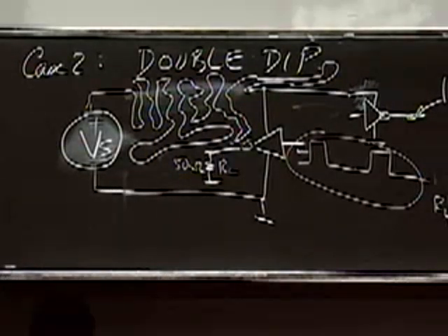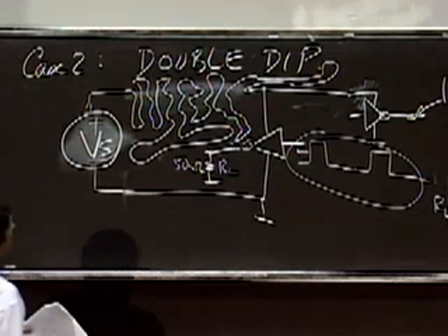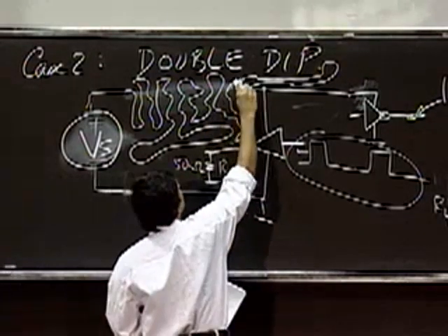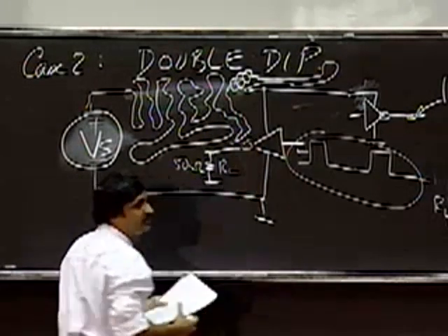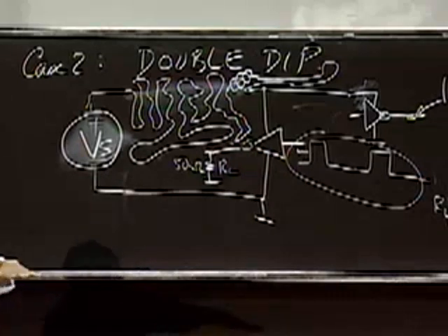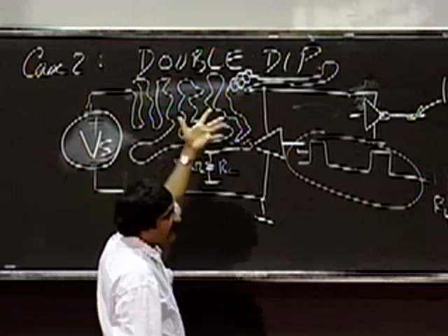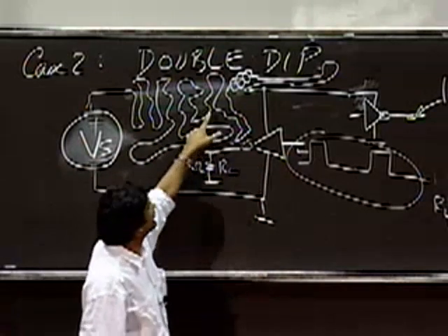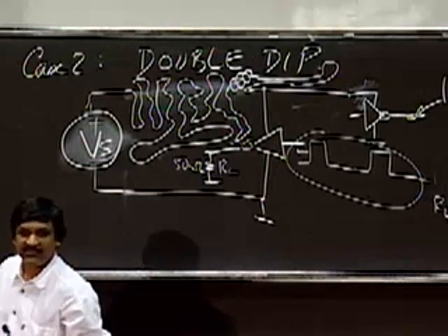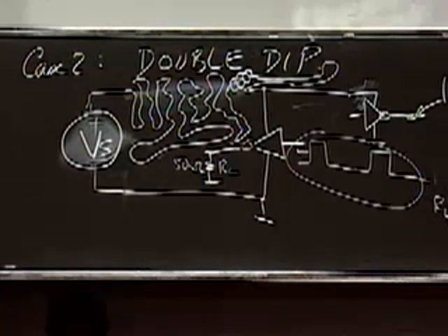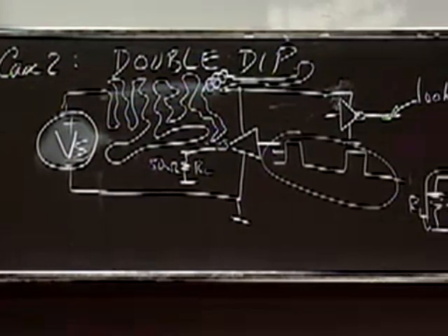So it's not the resistance. It's really, really thick. And it's a long wire. So a signal wire above a ground plane behaves like an inductor. Here, it has a capacitance too, but in this case, it's inductance. So there's an inductance here. I'll give you another 10 seconds to think about it, and then tell you the answer.